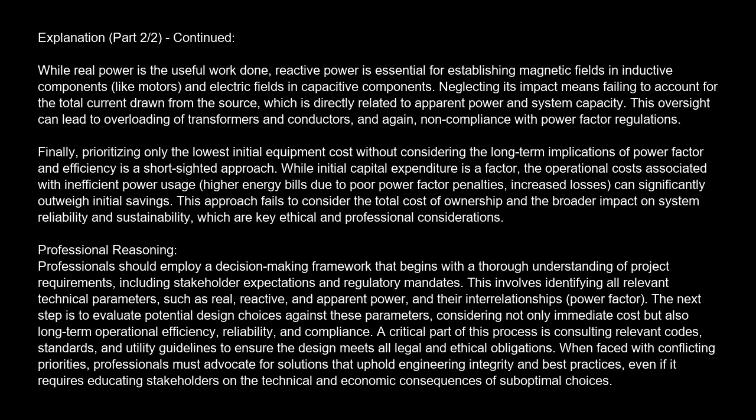Finally, prioritizing only the lowest initial equipment cost without considering the long-term implications of power factor and efficiency is a short-sighted approach. While initial capital expenditure is a factor, the operational costs associated with inefficient power usage, higher energy bills due to poor power factor penalties, increased losses, can significantly outweigh initial savings. This approach fails to consider the total cost of ownership and the broader impact on system reliability and sustainability, which are key ethical and professional considerations.